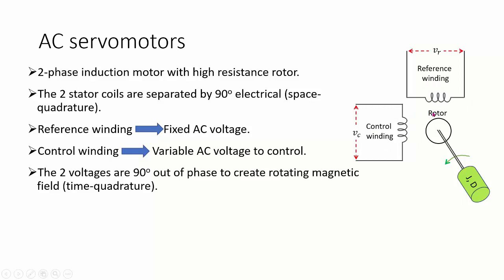These two fluxes should have a phase difference of more than 0 degrees in order to achieve a rotating field around the rotor. It's better that these two fluxes be 90 degrees apart to have the best rotating field at the rotor periphery.